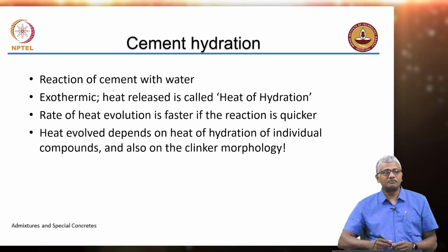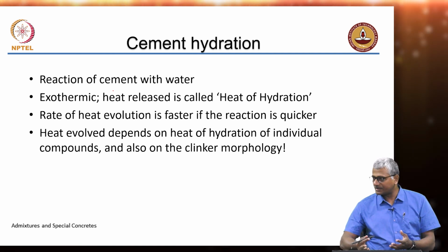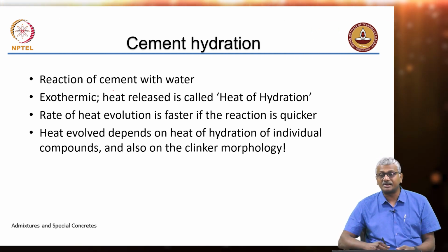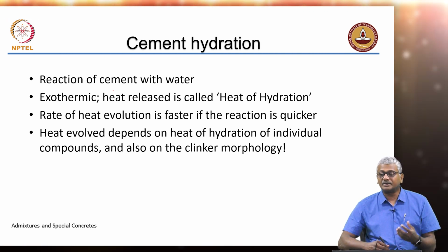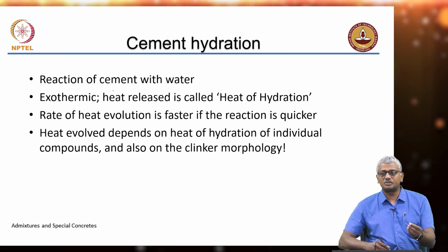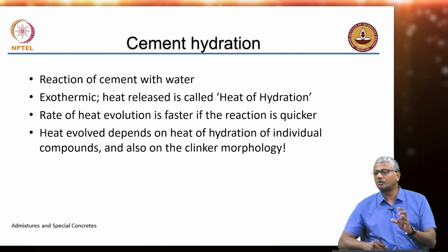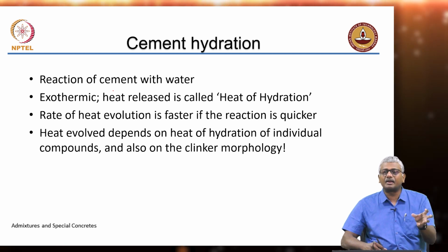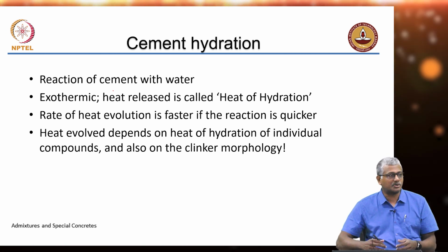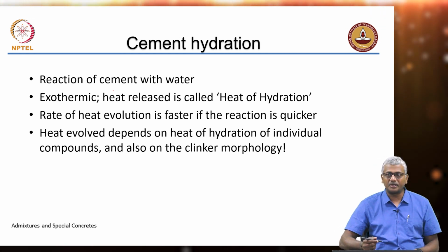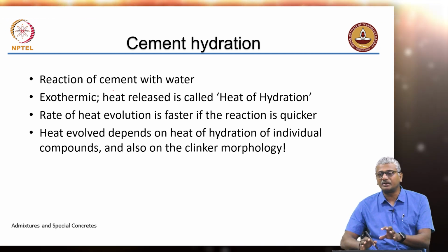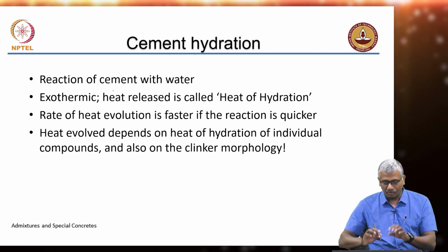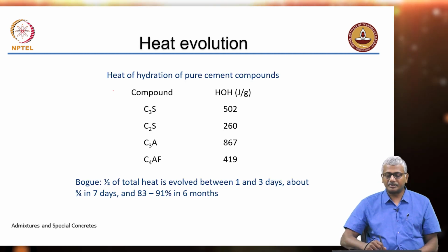Right. So, what is important for us to understand is, of course, that cement reacts with water. The process is called hydration. The process is exothermic, it releases heat, right, and the heat of hydration depends on each individual compound that is present and also the morphology. Why morphology? Because sometimes the degree of irregularity may be different depending upon the type of processing that happens inside the kiln, okay. So, again, those are aspects that we learn in a lot more detail in cement chemistry, but for now we will not really look at that in more detail.